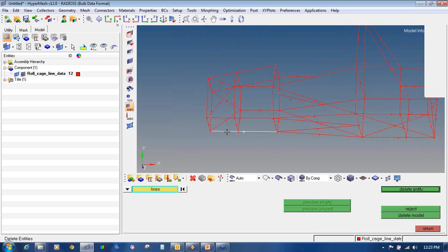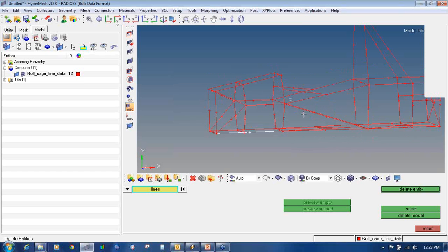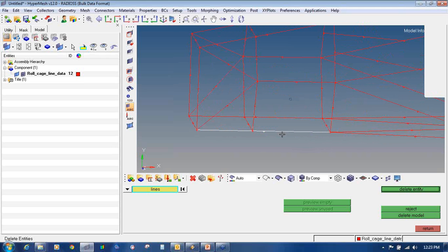The second option, doing the geometry editing first and then the meshing, is the best one, because if you want to change the element size, the mesh quality and different things, and the geometry is perfect, you need not change the meshing every time. So it will be easier for you. So I suggest you go for the geometry editing first and then the meshing.